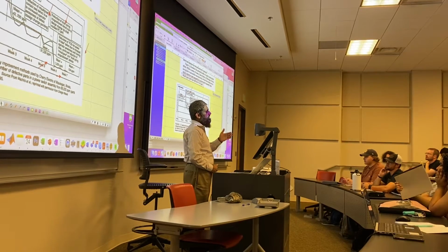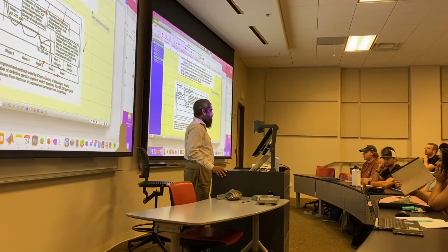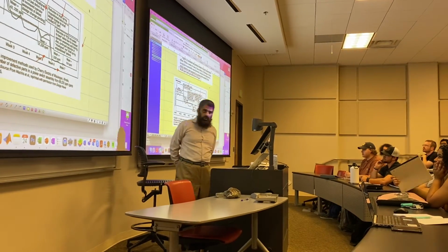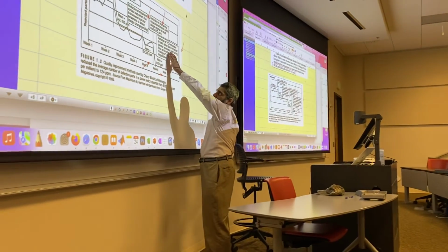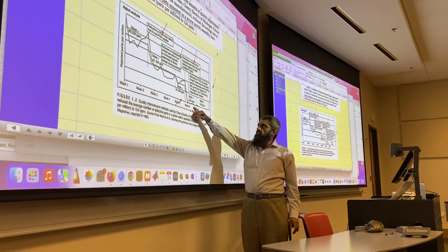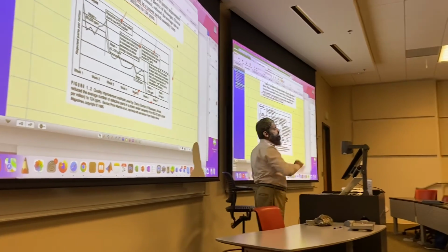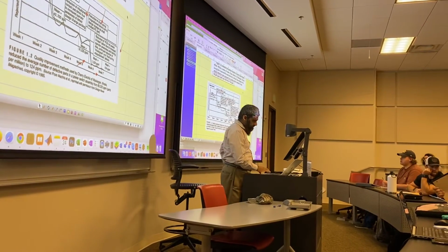If you follow this checklist, there will be less chance of having a defective part. Then they found another improvement: the PCB was not seated to the base. When they removed that defect, the defective parts went down to 124 parts per million. So that's an improvement method. Do you understand that?